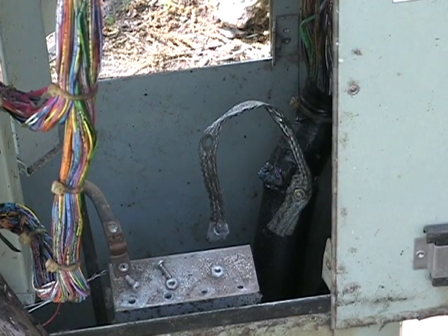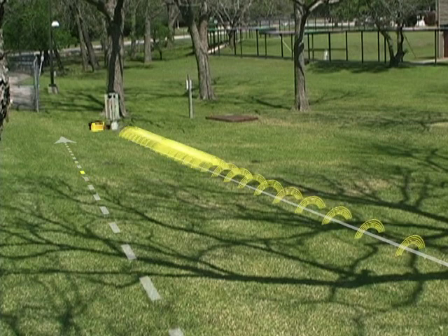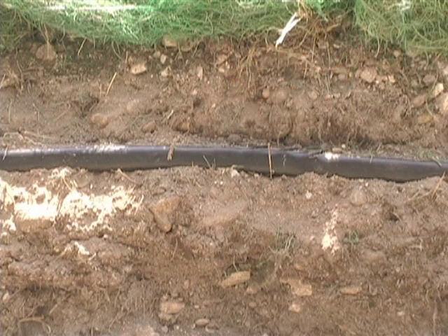When fault locating, the first step is to isolate both ends of the faulted section of cable. There should be no physical connection on either end of the cable. The transmitter is connected to one end of the faulted conductor. It sends a signal through the good portion of the conductor. When the signal encounters a fault, the signal returns through the dirt, back to the ground rod, and through the black lead of the transmitter to complete the circuit. Fault locating is pinpointing the spot at which the transmitted signal leaves the conductor and re-enters the ground.